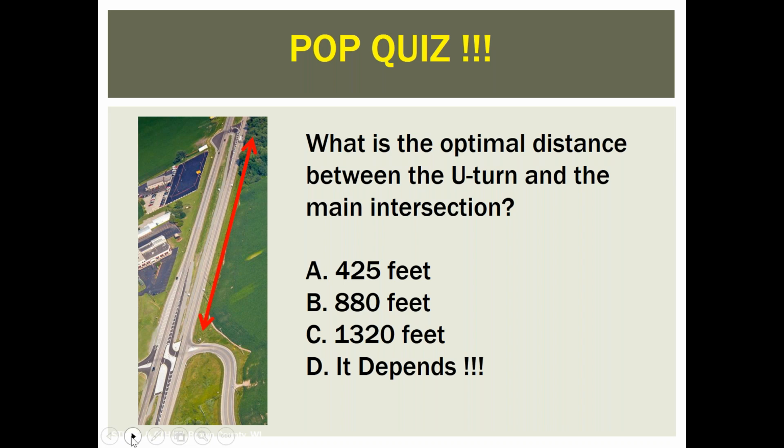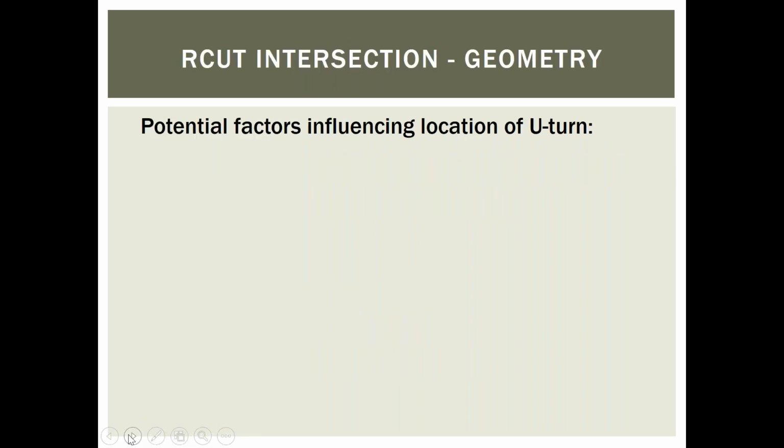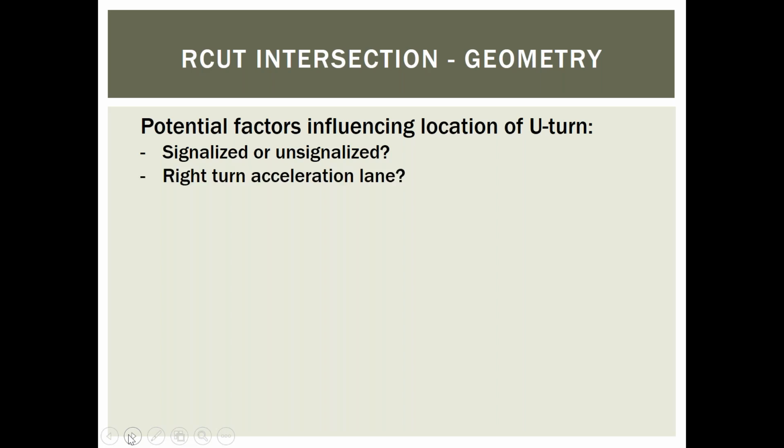Well, the answer is it depends. It's the answer to most things in life. Well, what does it depend on? Well, is it signalized or unsignalized? If it's signalized, the signals create the gaps. The U-turn bay can be closer in.